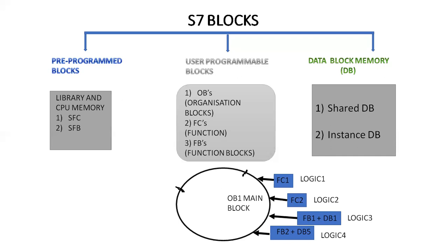Now here we are having shared DB and instance DB. Instance DB means FB plus DB. I'm giving some DB memory for that particular FB block. Whatever logic you write in that FB, that logic value or status, whatever the output is, will be stored in that DB memory. That DB is assigned for that particular FB only.